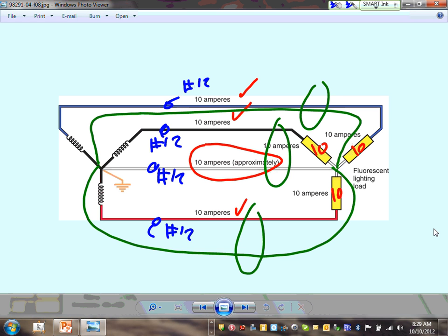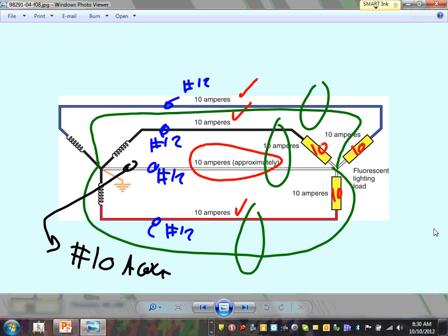That's an option. A third option we use in an industrial building, guys, is they take this neutral and make it number 10 AWG, so they make the neutral bigger. So that's a few solutions to solve the problem of harmonics. A lot of engineering firms pull a neutral with every phase. But if you know that this is your circuit load, and everything is rated for number 12, who cares if it's carrying 10 amps? It's already rated for it. Any comments, guys? Any questions about this issue?